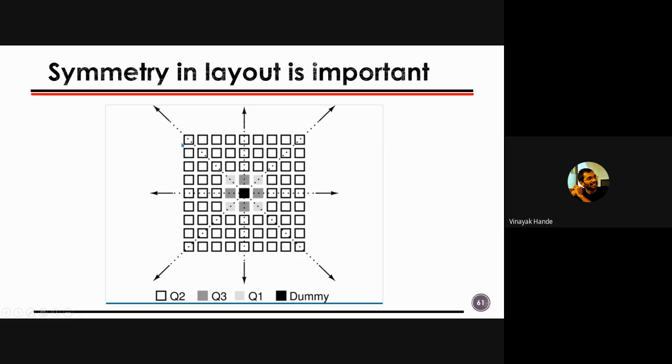So if your circuit is very, very sensitive to process variation, then it is definitely advisable to put some other transistor, which will make sure that this transistor will look like this transistor, right? Means this transistor will also feel that it is in the same environment as the transistor diagonally opposite to it, right? I think it is because of this precise reason people put the dummy.